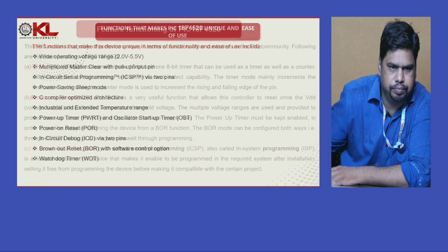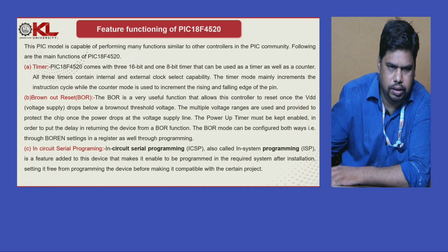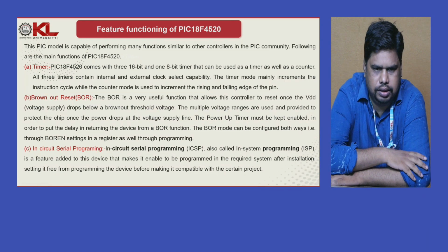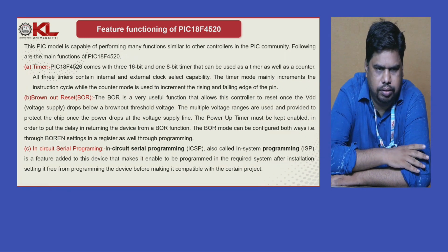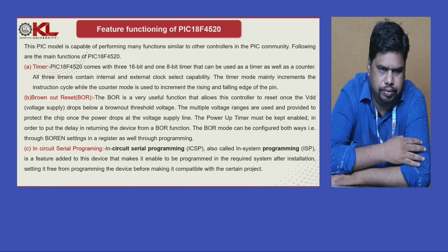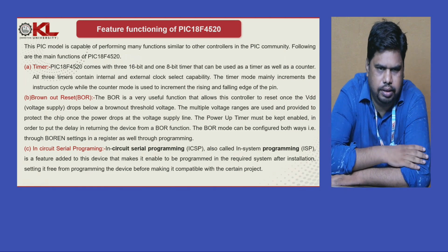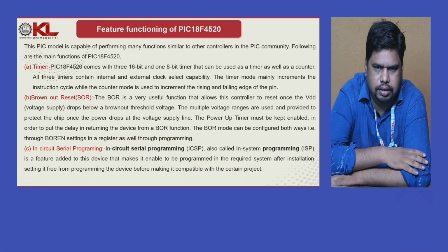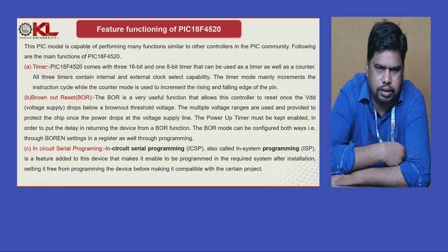Let's see the function of all these features available with this 18F4520 microcontroller. Timer: you know that the PIC 18F4520 comes with 4 timers, 3 16-bit and 1 8-bit, that can be used as a timer as well as a counter. All 3 timers contain internal and external clock select capability. The timer mode mainly increments on the instruction cycle, while the counter mode is used to increment on the rising and falling edges of the pin.